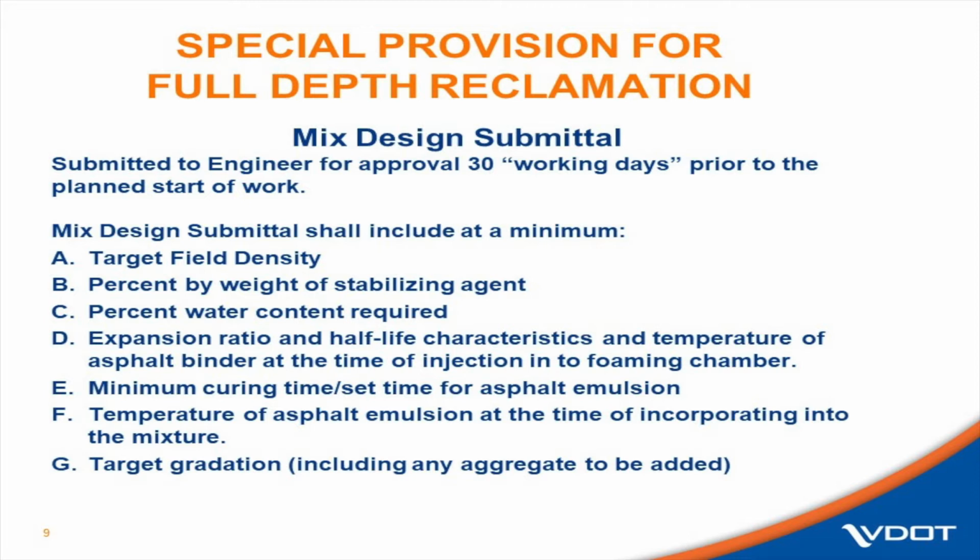The mix design submittal shall have at a minimum your target field density. That'll be your proctors for your stabilized material. Percent weight of the agent, whether it's 4% cement, 5%, 6%. The percent water required, moisture content of your mix, very important. The expansion ratio and half-life characteristics and temperature of asphalt binder at the time of injection in the foaming.